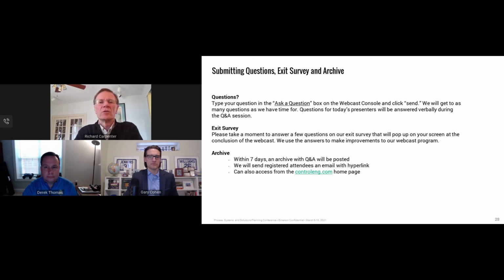It's traveling 2 millimeters less every month, and so as a result, I'm producing more quality problems than I expect, right? So I think you start with the problems you're trying to solve. You assess whether you have the information to be able to understand the problem, and if not, you start to instrument the equipment to get that data.